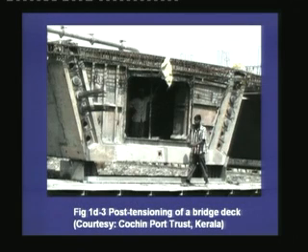A similar section, after it has been post-tensioned: you can observe that the tendons are sticking out from the end blocks, and once the full post-tensioning operation is done in one duct, then the excess amount of the tendons are cut off, and this end anchorage block may be covered with grout, so that it is not subjected to corrosion.